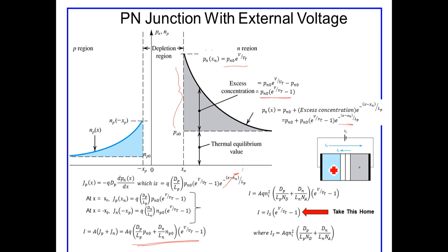Clearly, from the perspective of the outside source, there is just a single current flowing. We have this legacy concept of a positive charge flowing. In reality, we know that it's electrons flowing from the negative terminal of the voltage source. And so we have this source that's supplying the electrons, that as the holes diffuse and recombine here, we have a continuous supply of electrons.